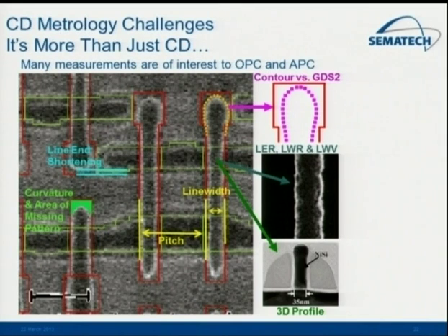But then you are also measuring two-dimensional features. So you've designed this shape to have this squared-off profile here, represented by the red line. In reality, it's not going to print that way. You can't get that much information through the lithography tool lens. So you're going to want to know what's the actual shape that it turned out to be. That will end up affecting overlay measurements as well. Or whether the line is shortened, or whether there are actually pattern parts that are missing. So these are all things you really want to extract as part of your measurement, in addition to just the line width. Ideally, you'd like to know the 3D profile, but of course, from a top-down view, that's quite difficult to get from this technique.